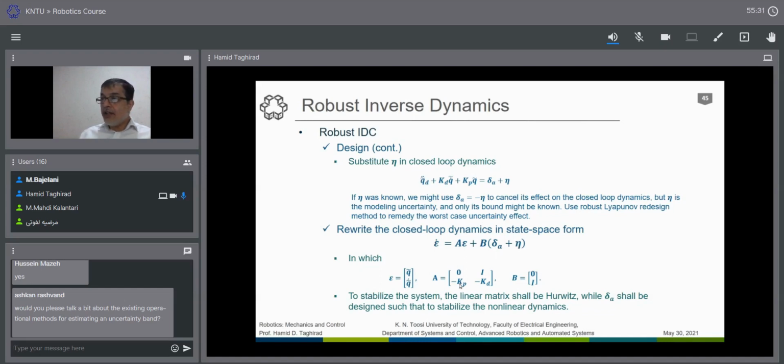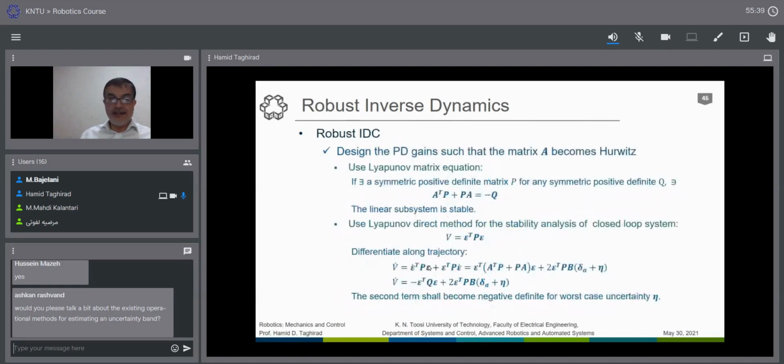performance. So we can consider this linear term by its eigenvalues, or we can use the Lyapunov matrix equation for that. And it is much more effective, as we saw in modern control, that Lyapunov matrix equation, which is A transpose P plus P A is equal to minus Q. If we can find any positive matrix P that can solve this Lyapunov matrix equation, then the system is always stable. And this is important because we use the P and Q in the rest of the analysis.